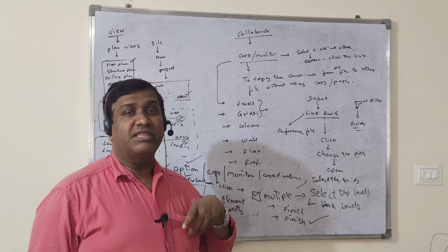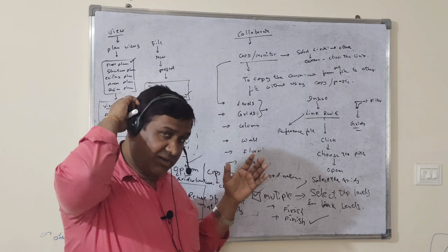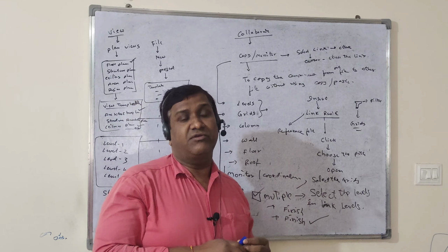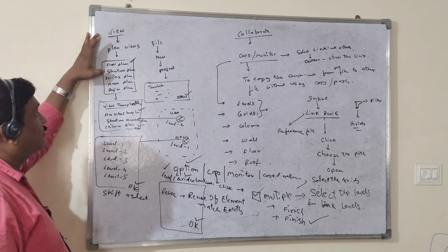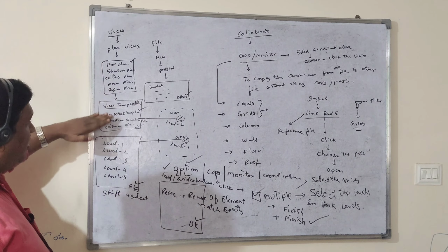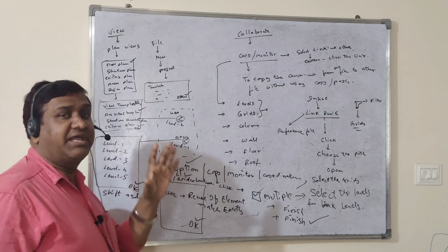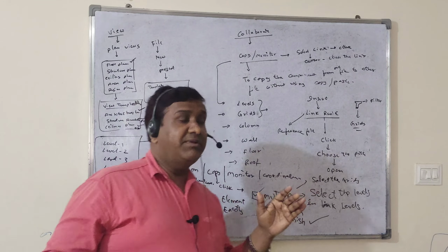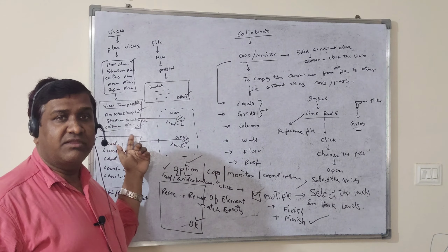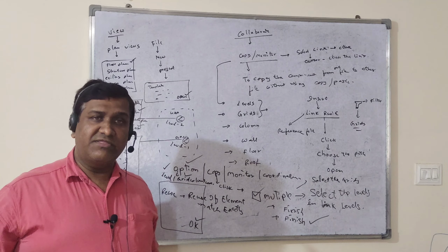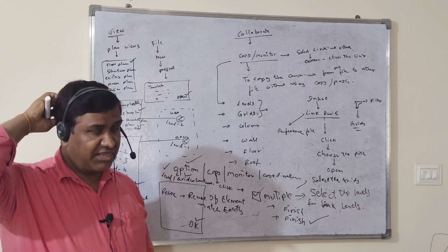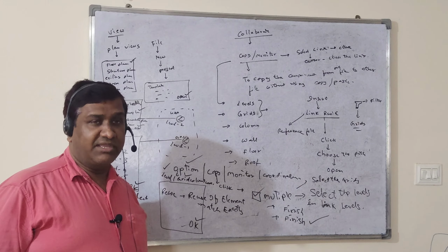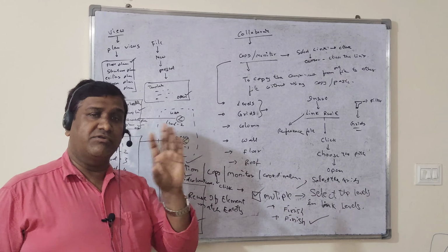So this way the architecture team develops the model, and the MEP team also develops theirs. But you have to follow the views here, because in the views, all the floor plans, 3D plans, structure plans and section plans are assigned with view templates. So again you have to go to view templates, make the property settings and visibility settings, everything, and work out the same.